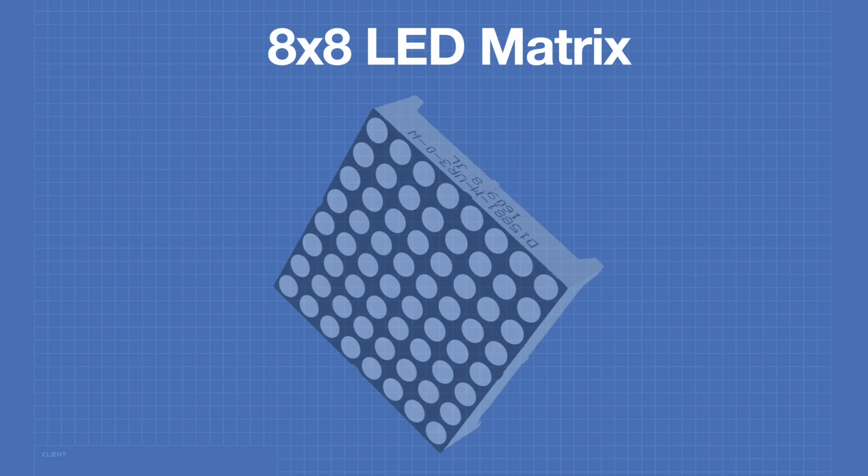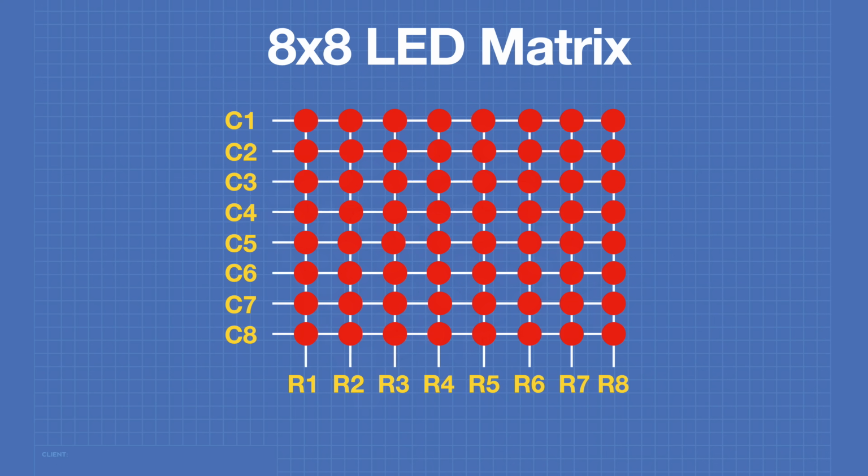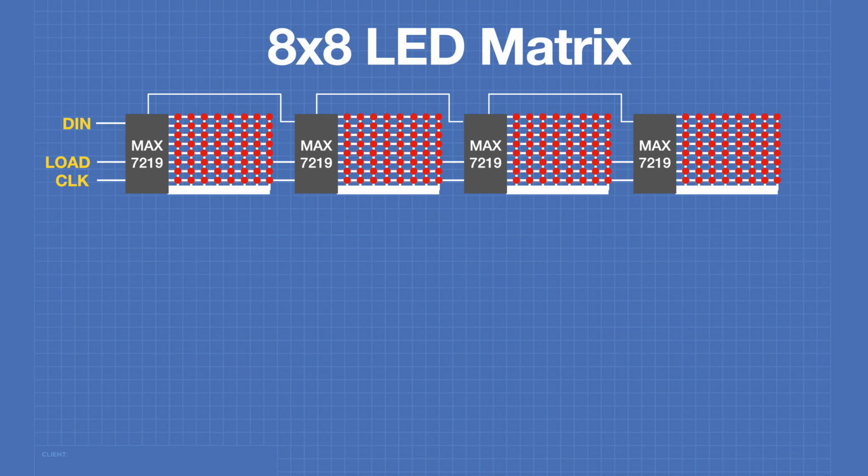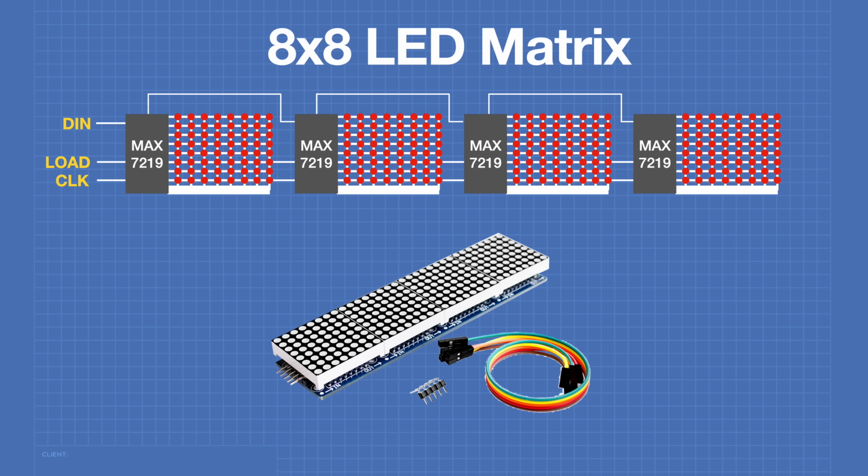An LED matrix display is much more versatile than a 7-segment display, as not only can it display numbers, it can display letters in both upper and lower case, plus a number of special symbols. These displays consist of 64 LEDs arranged on an 8x8 matrix. The LEDs can be addressed by row and column. This is a perfect match for the MAX7219, and so many of these displays are available with the MAX7219. The display I'll be using today consists of 4 8x8 LED matrices. Each matrix has its own MAX7219, and they are cascaded as shown here. You can also use individual displays if you wish.